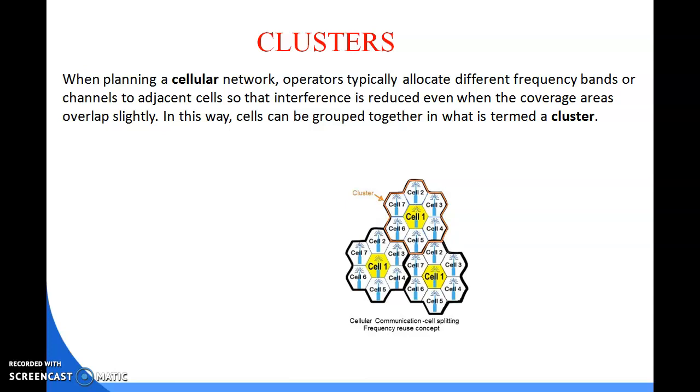Right, but there is also the fixed channel allocation scheme, which is used in GSM mobile phones. But the problem is that before allocating the frequency, though it is fixed, first we thoroughly analyze the traffic situation or traffic positions of those cells or clusters, because once you have allocated, you cannot change or borrow the frequencies from the neighbors, right?